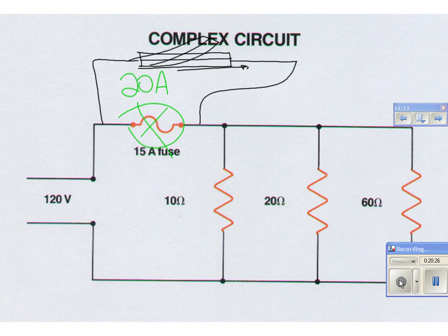In a true circuit breaker, there's some springs and some levers and some latches so that when it gets too hot, it starts to bend, and then it goes pop, and it flips open, and it stays open. So you have to walk into your garage and open the circuit breaker box and find the one that's flipped the switch and switch it back. And that closes it so that your circuit works again. If you have not turned off any devices, like your hairdryer and your blender, it'll pop it again. So what you do is you turn off some devices, and then you turn it on, and everything works. That's the way modern circuit breakers work.